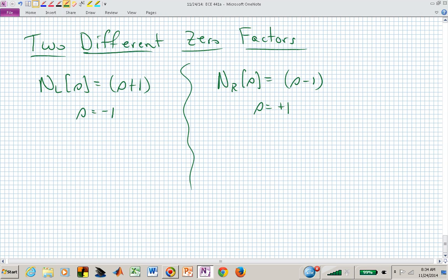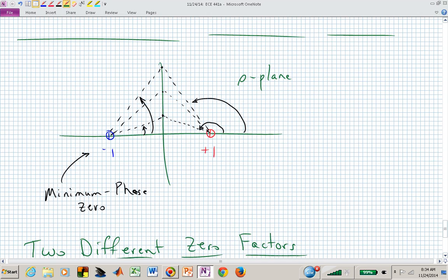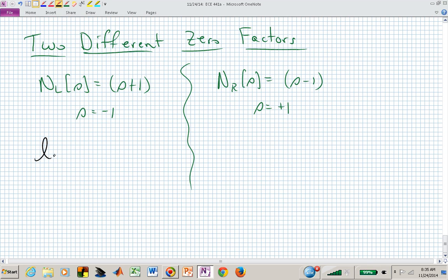If I labeled these as, let's say, L sub ZL for the length of the 0 in the left half plane, or this is L sub Z right, the distance is now this length, and over here, just by replacing S with j omega, now we're comparing the magnitude of j omega plus 1 with the magnitude of j omega minus 1.